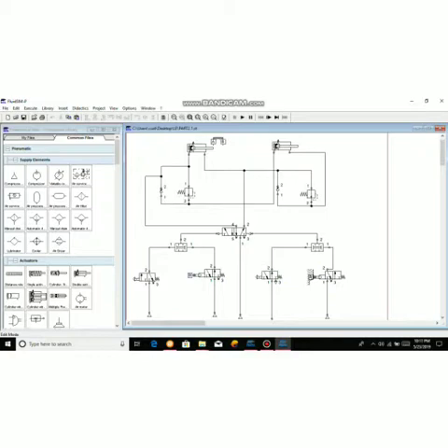where I will discuss the function of its components. It contains two double acting cylinders, a 5/2 impulse valve, two pressure control valves, four 3/2 way valves, and two sources of air. For each function, I will explain.